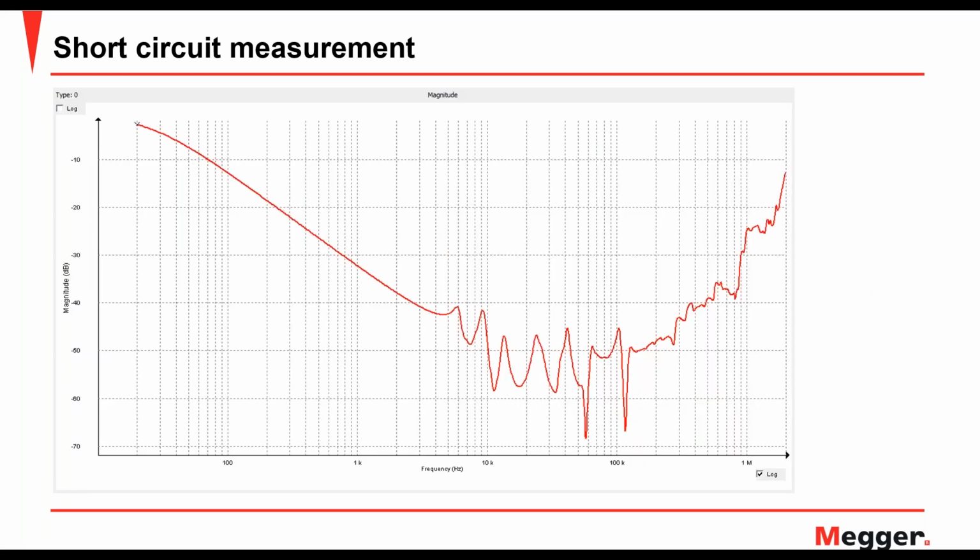So this again is the same plot. This plot, like the earlier plots, is the magnitude of the transfer function expressed in decibels, right? So we are looking at the ratio of the output signal to the input signal. Now, instead of looking at the magnitude of the transfer function, we can also express the same data points in terms of impedance. We do know what the measurement impedance is. The typical standard is 50 ohms.